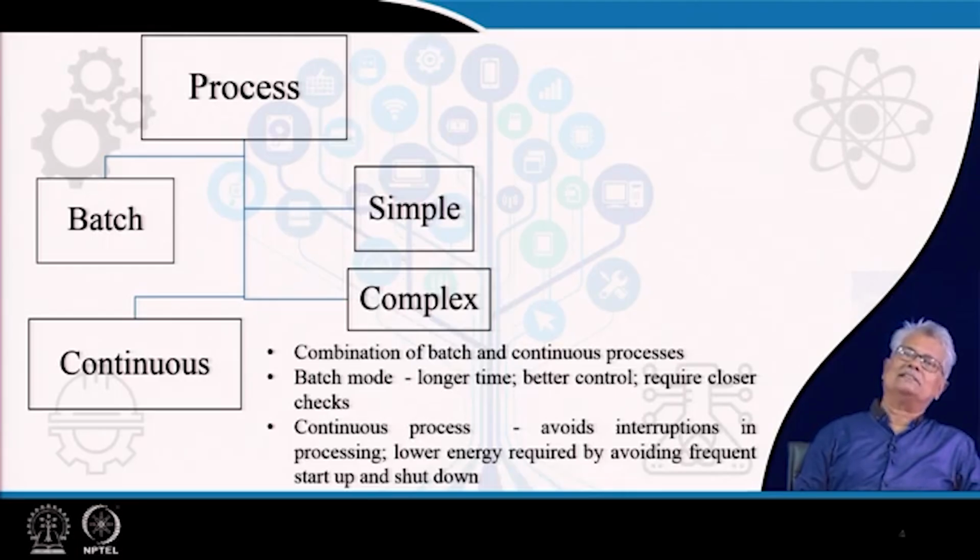The first thing, since the entire batch feed has to be held in the same equipment as the batch starts, the batch equipment for the same capacity per day will be much larger in size. In case of a continuous plant, for example, if I am processing 10 tons per day, the capacity of processing will be 10 divided by 24 hours, roughly slightly less than 0.5 tons per hour. So, quite naturally at a time I will be having a much smaller quantity of hold up in case of continuous equipment, and my process equipment size is going to be much smaller.